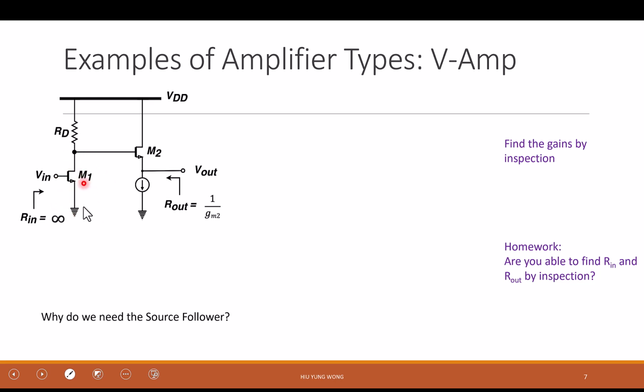Just think of it. What type of transistor is this? NMOS, yeah? And then you start with what we learned at the very beginning. The highest potential is drain, right? The lower potential is source. And this is gate. And then now, yes, this is not the output of this whole circuit, but this is something I give to the next stage, right? So this is the output of this circuit, right? So input is gate, output is drain. So this is what type? Common source, like what you said, right?